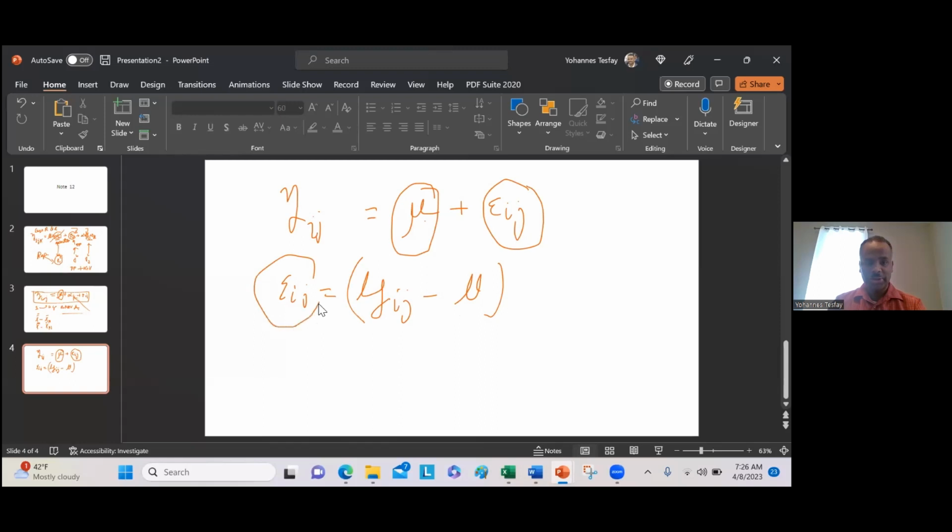So when we calculate the standard deviation for this one, that means the sum of y ij minus y bar, because we fix one part, the whole square over n minus 1. This is sigma square, and this is the repeatability. Just fix one part and run it.